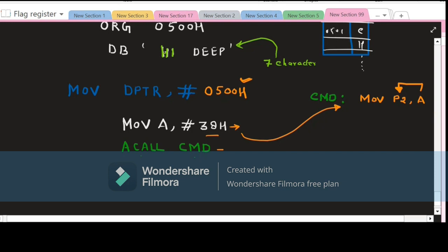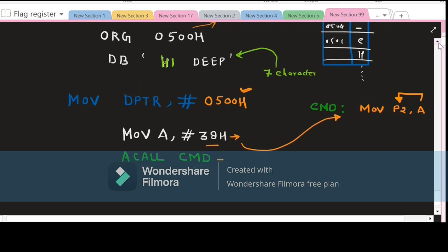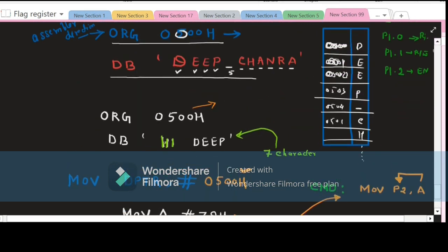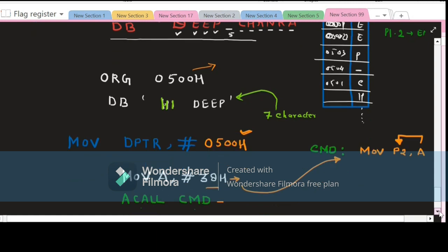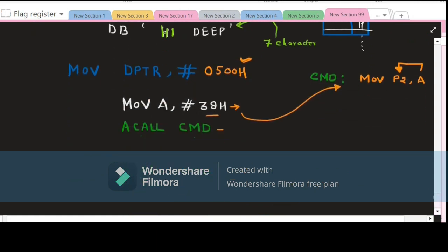Now, okay, now we will see. First of all, tell me whether it is a command or data. So this is a command. Which pin do you want to set, that is, will RS be 1 or 0? What register will you select? We will select the command register. To select the command register, RS should be 0 or 1? RS should be 0. That means RS should be 0 to select the command register. That means you have to clear, CLR,